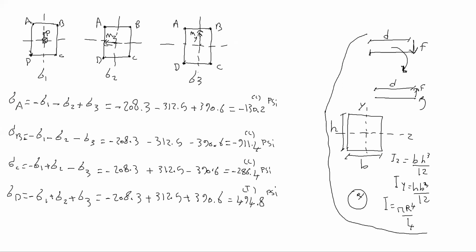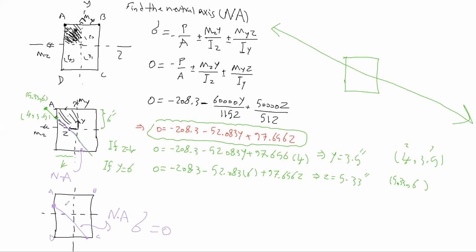So yeah, you can analyze that one. If you compare this figure with the equation, in the area that includes A we have these points where sigma 1, sigma 2, sigma 3, if we add all of them, cancel each other and reach zero stress. These points are on the neutral axis in this quadrant, but the neutral axis doesn't pass through this region. By the way, this purple line is the neutral axis.